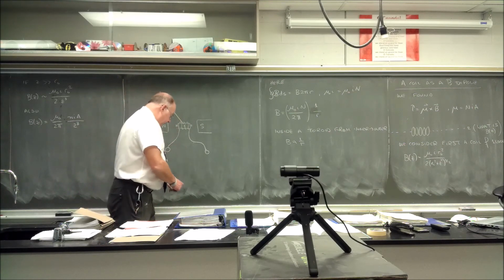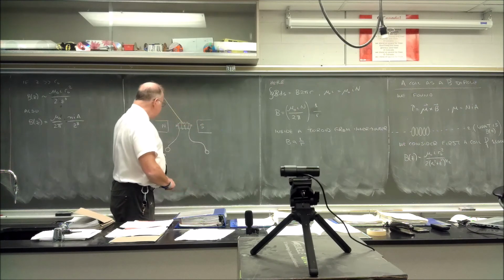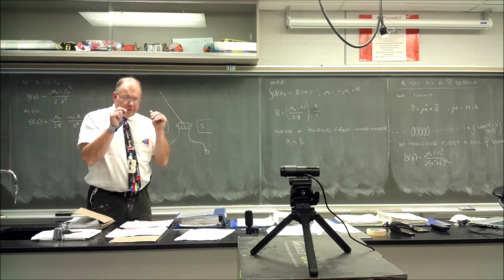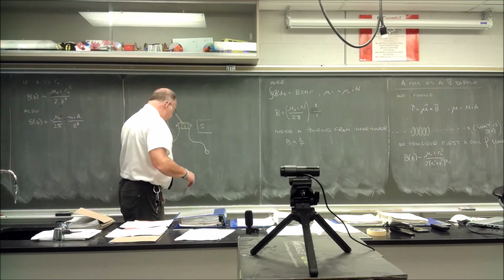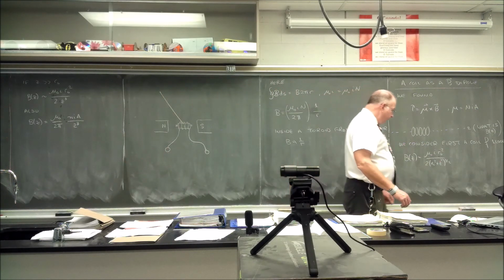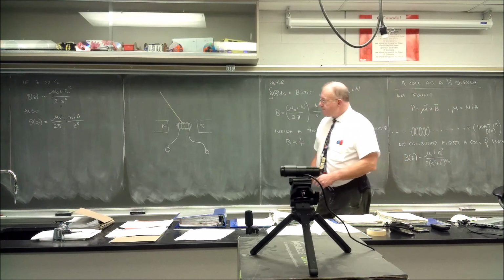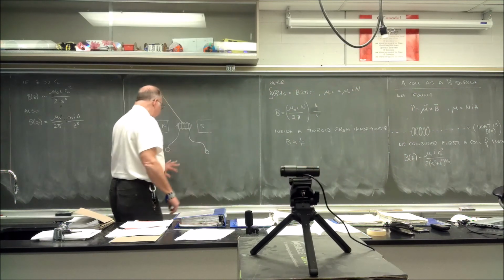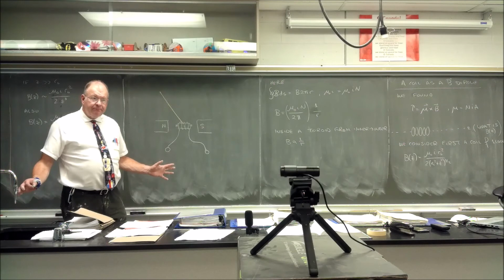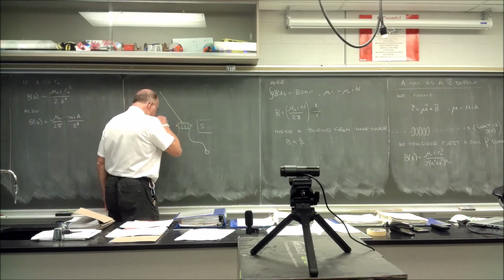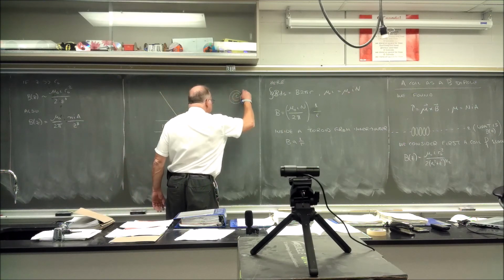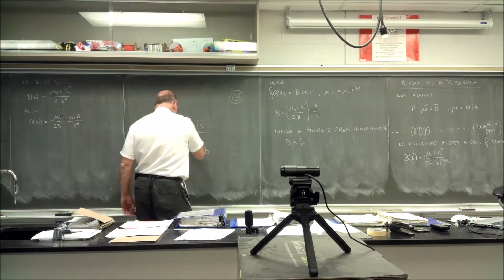Now, I haven't finished this yet because right now, these bearings that hold this are very, very fine, very, very low resistance bearings. You'll often see meters in those days with, say, 7 joules or something like that. They mean that based on the movement apparatus. Now, as it is, if I energize this, it's going to slam over here. That's going to be it. And we're not going to get anywhere. So instead what we do is we put a watch spring in here. I'm going to get the right direction. So a second here. Yeah, that's the way.